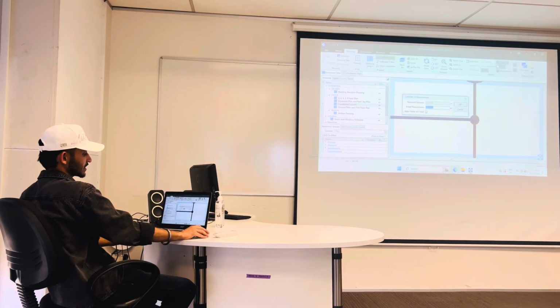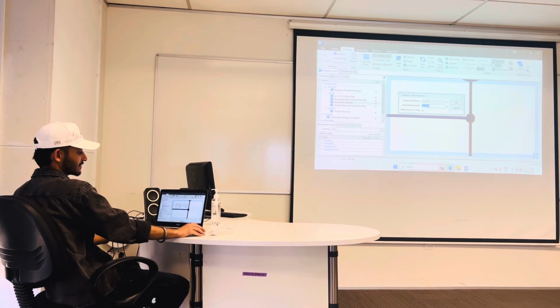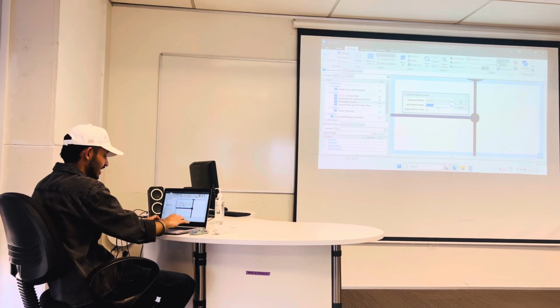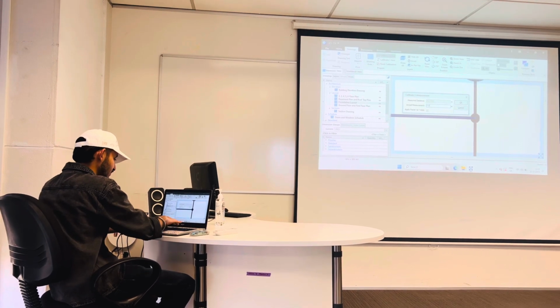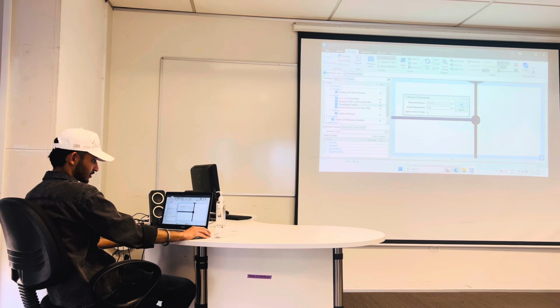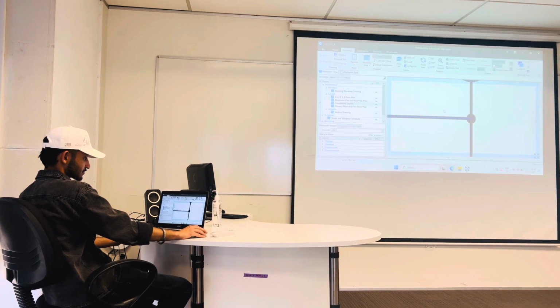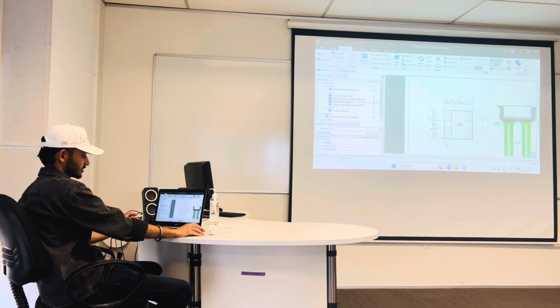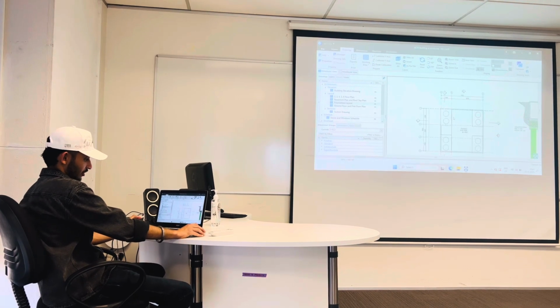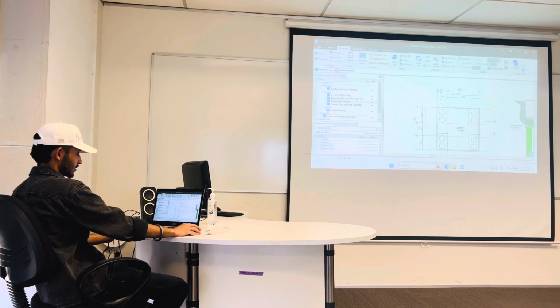Now the digital measurement is showing 73.5753 meters, but the actual measurement is 7.42 meters. We'll apply this and do OK and yes. As our drawing is calibrated, now we will move to the dimension page.